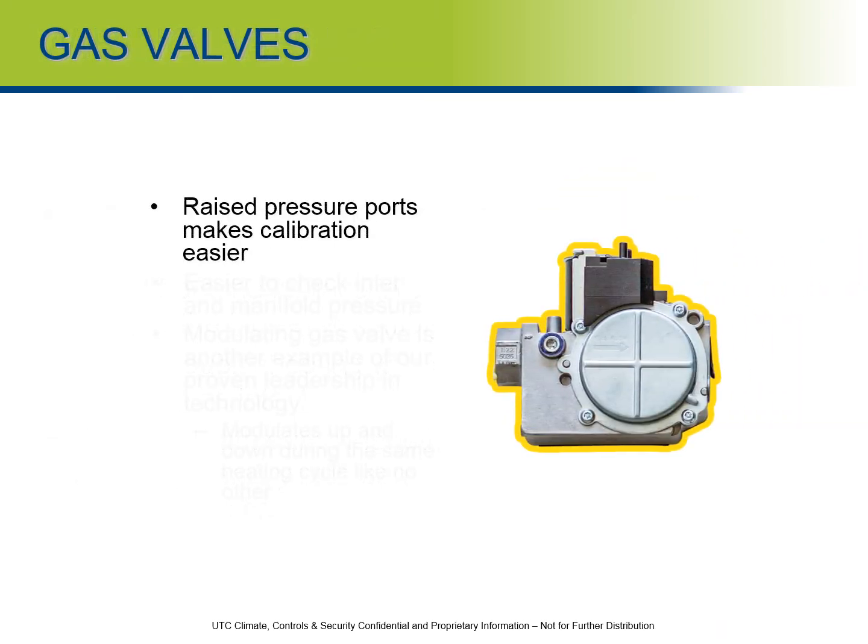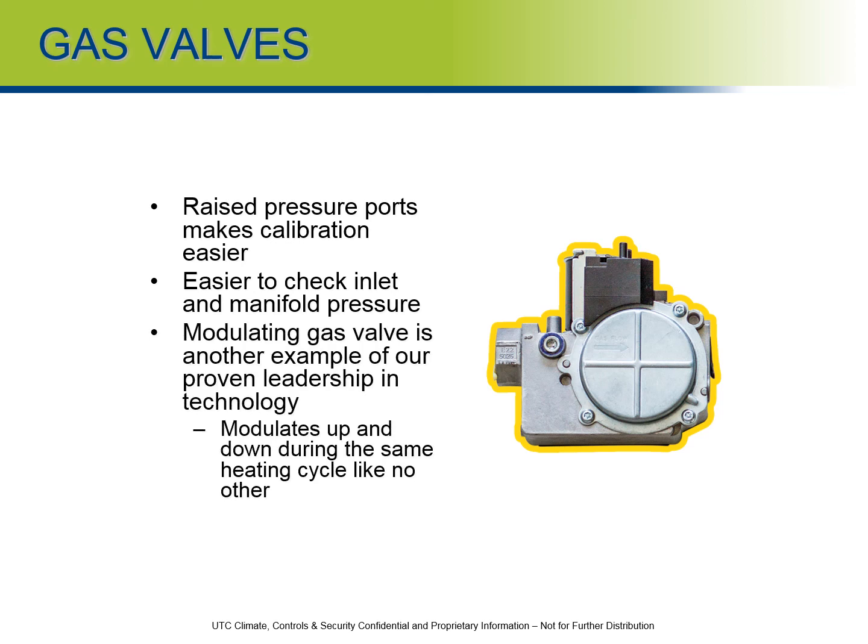Gas valves. At this point, most of your installers or service technicians are aware that the pressure ports on the gas valves have been raised to make for an easier connection. It makes adjustments easier on the gas valve, and much easier to check inlet and outlet gas pressure. The modulating gas valve is just another example of the proven leadership and technology in the equipment. It modulates up and down during the same cycle, like nobody else out there has.